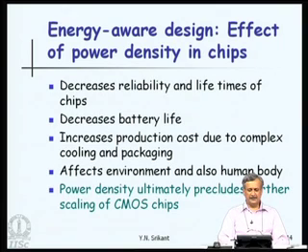But increasing the power density in chips decreases reliability and lifetimes of chips, it decreases battery life, it increases production cost due to complex cooling and packaging, it affects environment and the human body. Power density ultimately precludes further scaling of CMOS chips. I already mentioned this.